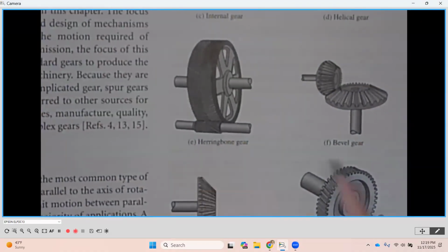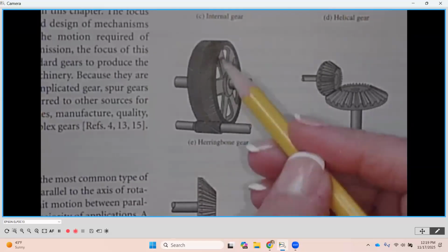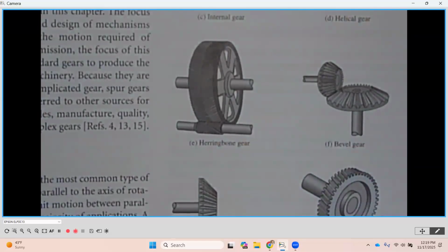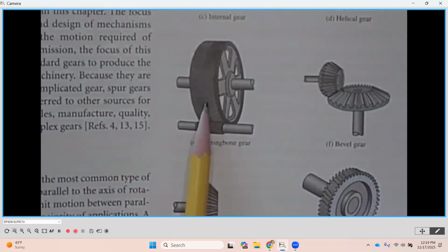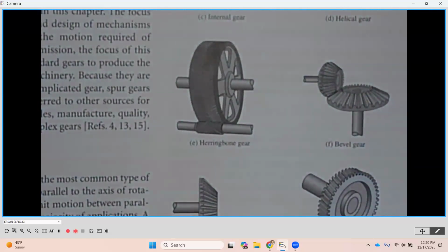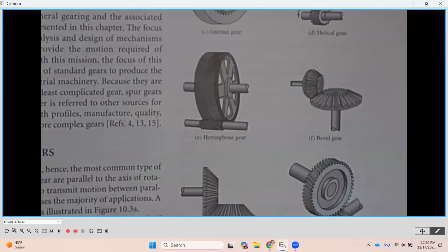The pinion would then also mesh or match up with that. Here again, we're going to have multiple teeth in engagement. It's a quieter gear set. It allows us to push more torque through for a low profile gear tooth. So usually the benefit here is you're going to have a wider gear, but the profile this way is going to be much shorter. Okay, and in some applications, it's needed.